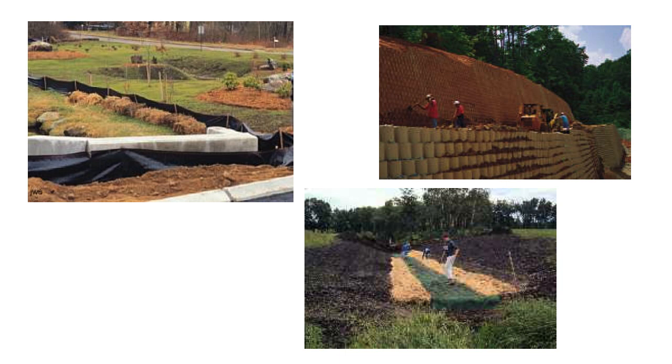Some development may nonetheless generate permanent soil and sediment loss. Long-term controls may be required for these sites. Best management practices include settlement, infiltration, and wetland basins, and must be sized relative to the amount of estimated sediment from the universal soil loss equation. Permanent controls are designed to last 50 years or more and typically require little maintenance. In practice, they rarely achieve this longevity, may consume valuable land space, and also may be expensive to construct.